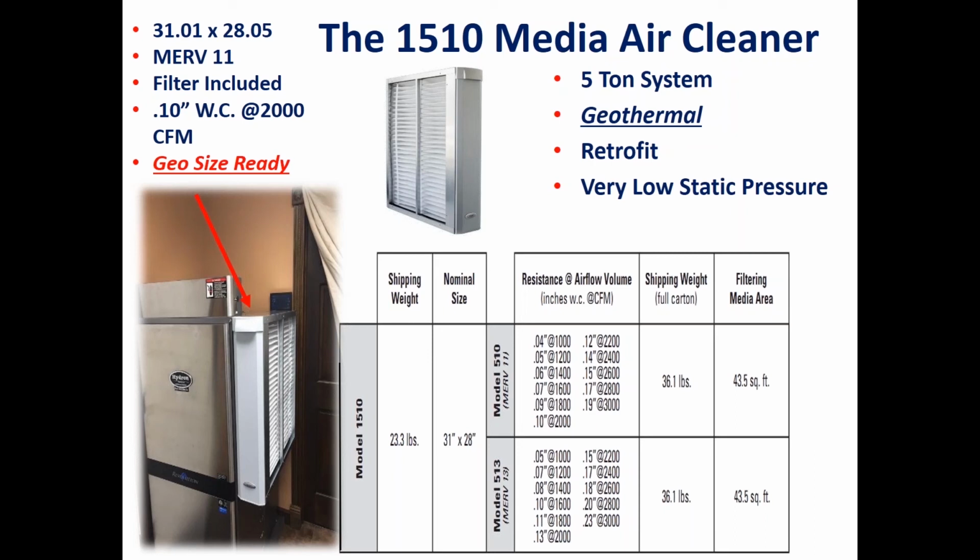At 2000 CFM, 5 tons, we're only at 1/10 of an inch, 0.1 inches water column at a MERV 11. That's industry-leading low static pressure. You're not going to find a MERV 11 filter that has that low of a static pressure.